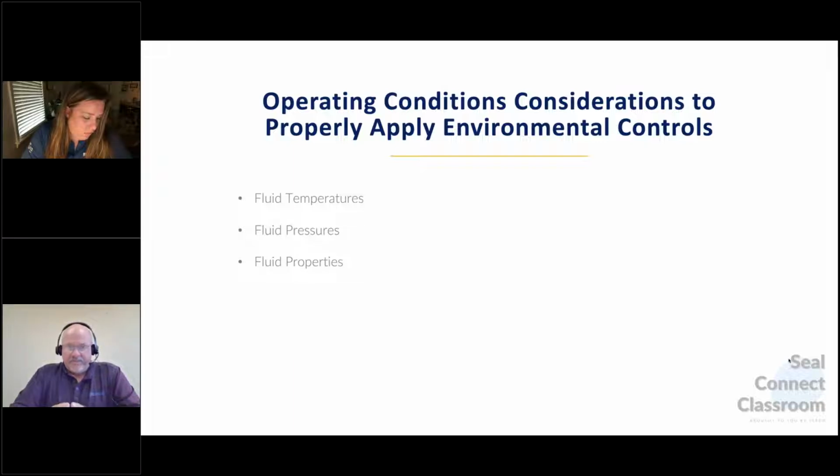So by those design limitations, we make components that are very, very thin walled, that are subject to changes in fluid temperature from expansion and contraction. In other words, if you've got carbon holders and holders that are holding faces, when you put them under extreme temperatures, we have to take into consideration expansion and contraction of the holders that we press the components in.